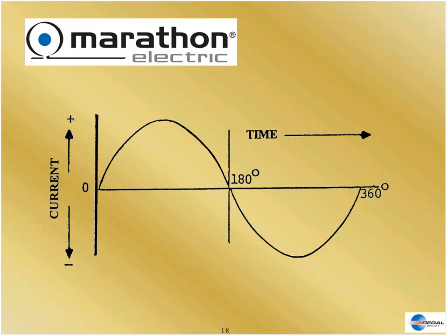Now we're back to our friend single phase. It rises and falls. It can't travel. How are we going to make this wave go around our stator with only one phase? Well, the way we do it is we artificially get this thing to move off of these dead center points by using an auxiliary winding, which is usually called a start winding.